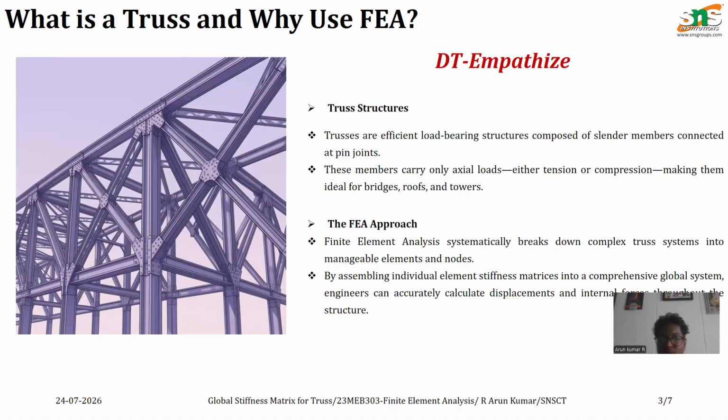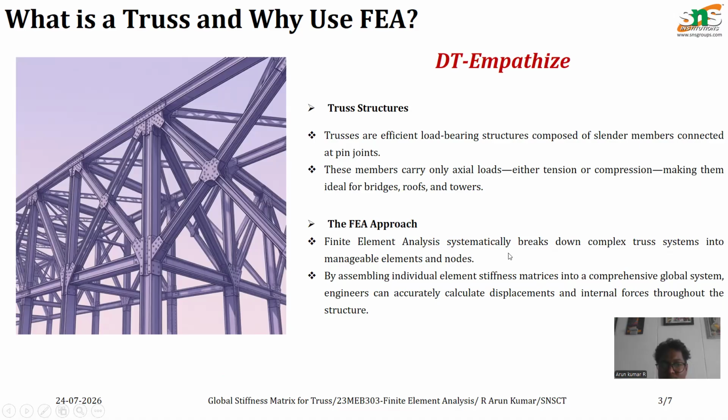So what is the FEA approach? Finite element analysis systematically breaks down the complex truss system into manageable elements and nodes. By assembling the individual element stiffness matrices into the comprehensive global stiffness system, engineers can accurately calculate the displacements and the internal forces in these structures.